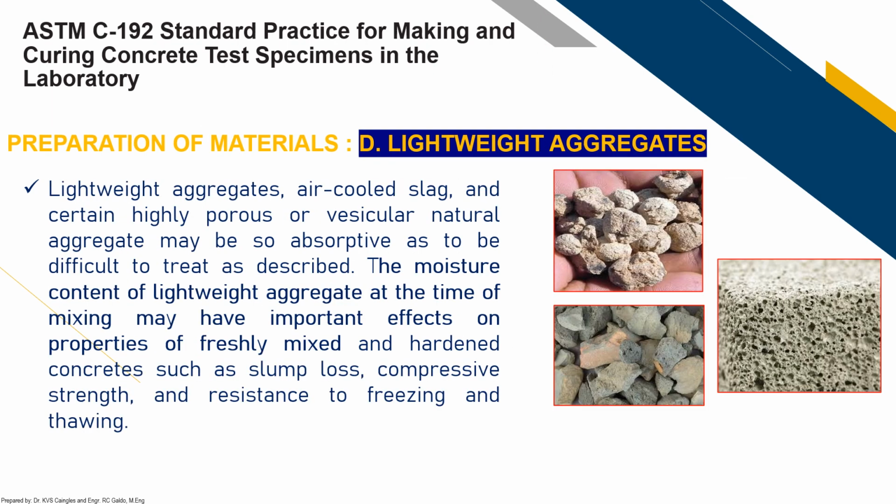Okay, the same goes with lightweight aggregates as well. But most importantly for lightweight aggregates, we really have to determine their moisture content or moisture characteristics, because these lightweight aggregates are considered highly porous and highly absorptive. Given that, they can absorb water when mixed with concrete, together with water and cement.